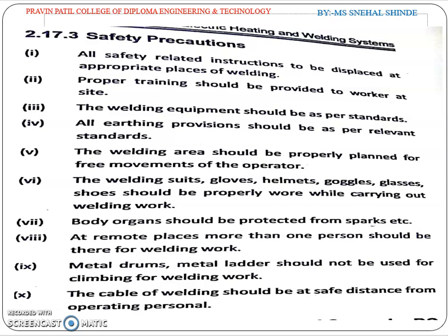And the next point is, at remote places, more than one person should be there for welding work. Not a single person should perform welding work, because if there are chances of a fault or some accident, you have to be alert and need another person who knows the welding work.